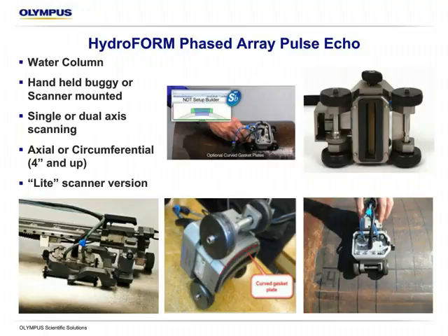The reason we use water in this application is that it offers the best ability to couple to the surface, especially on rougher in-service surfaces, where the surface condition even after UT prep might not be perfect. So water offers a great medium for that, and also pretty good near-surface resolution, which we'll talk about collectively a little bit later. We're able to change these plates out. After a period of time, if the plates or the gasket get worn out from scanning or running over some spatter or something like that, it's a toolless design. We just have extras of these in the kit. You slap a new gasket on and you continue to go.